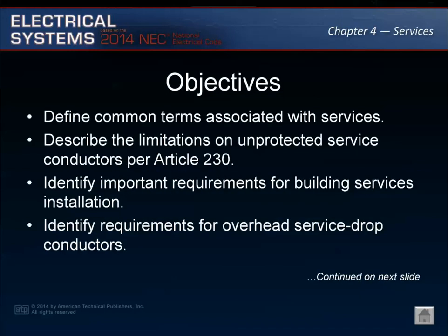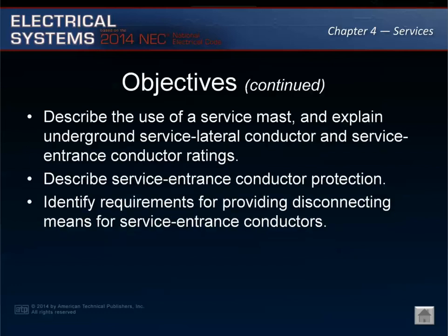Upon completing this chapter, you will be able to define the common terms associated with services, describe the limitations on unprotected service conductors per Article 230, identify important requirements for building services installation, identify requirements for overhead service drop conductors, describe the use of a service mast, and explain underground service lateral conductor and service entrance conductor ratings. Describe service entrance conductor protection. Identify requirements for providing disconnecting means for service entrance conductors.